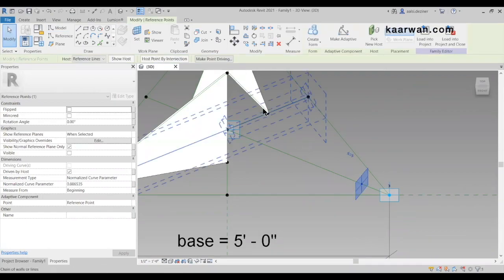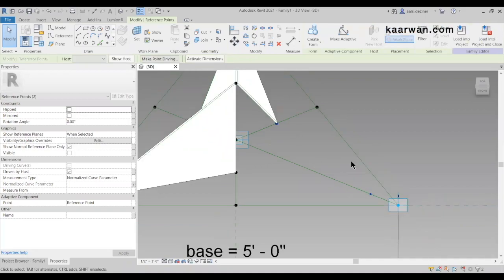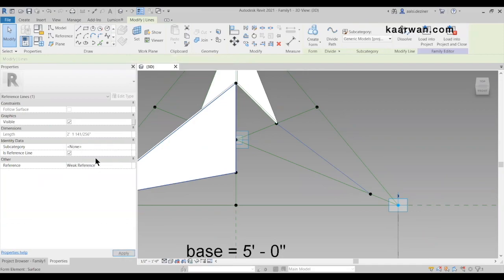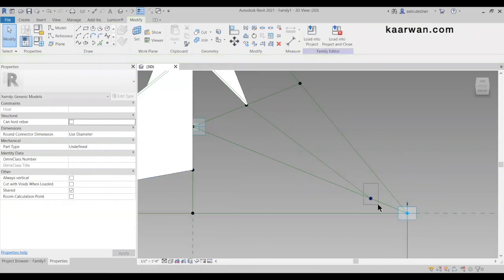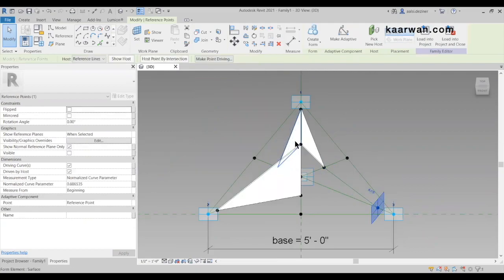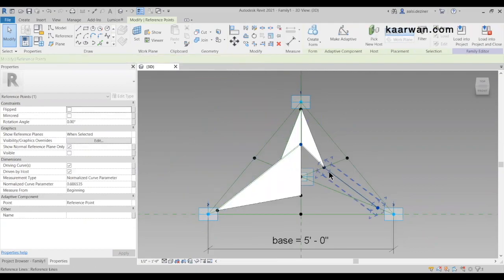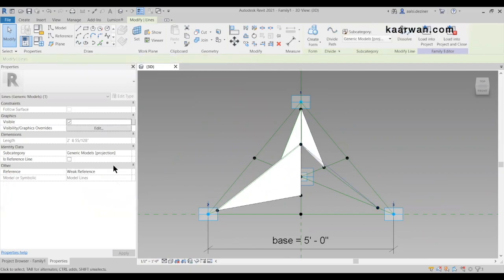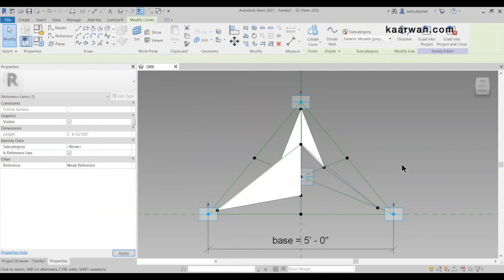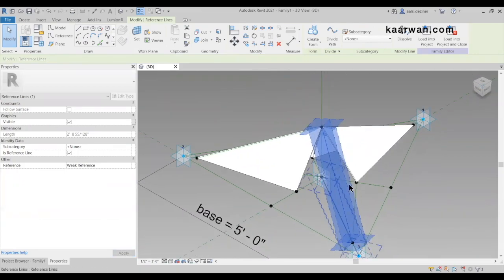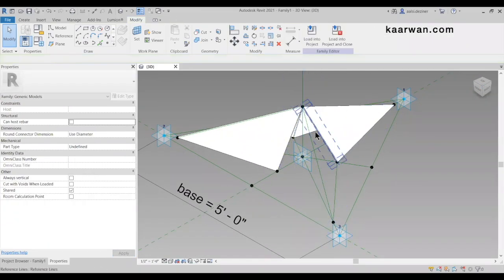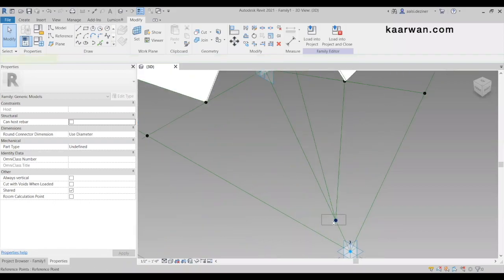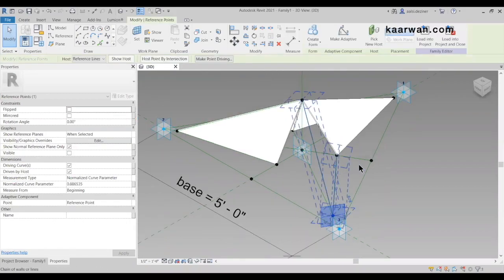Next, select this point. And select this earlier point. Line through two points again. Into a reference line. Select the new point. Find the vertical point. Make sure you select these two and draw a spline here and make that spline into a reference line. Okay. So have a better look. You can see this is a reference line.